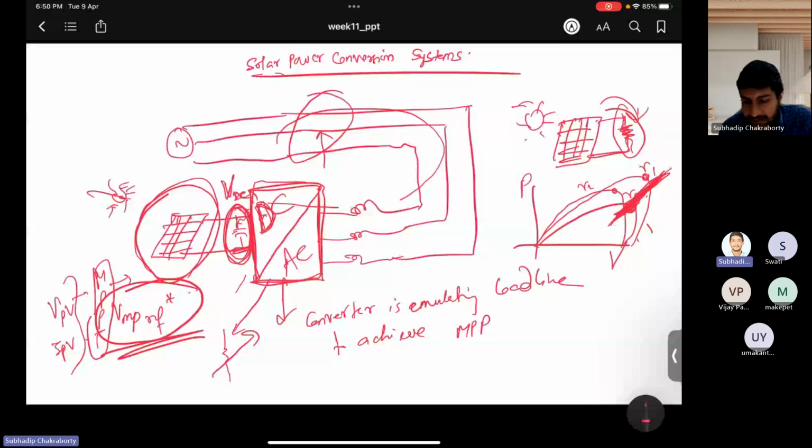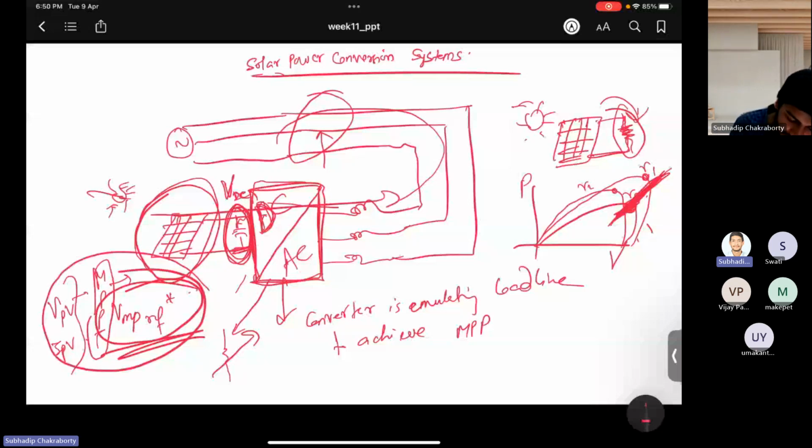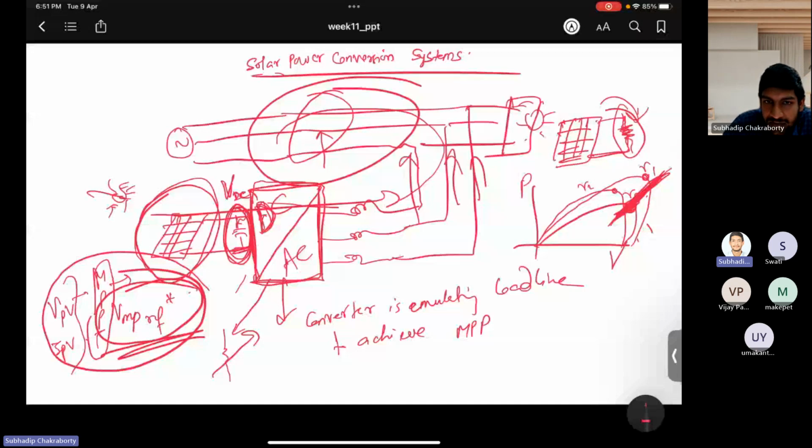You also have this multifunctional ability where you can control the inverter to achieve sinusoidal grid currents, irrespective of the distortion in the connected loads that we already discussed in the DStatCom controls. Where you have loads of irregular nature, you can also embed multifunctional controls into the converters such that you achieve the maximum power point of the PV, as well as you can throw maximum power at unity power factor, balanced grid currents where there is no harmonic distortion of the loads reflected into the grid. So you can also regulate the grid currents in parallel such that you can achieve improved power quality operation.